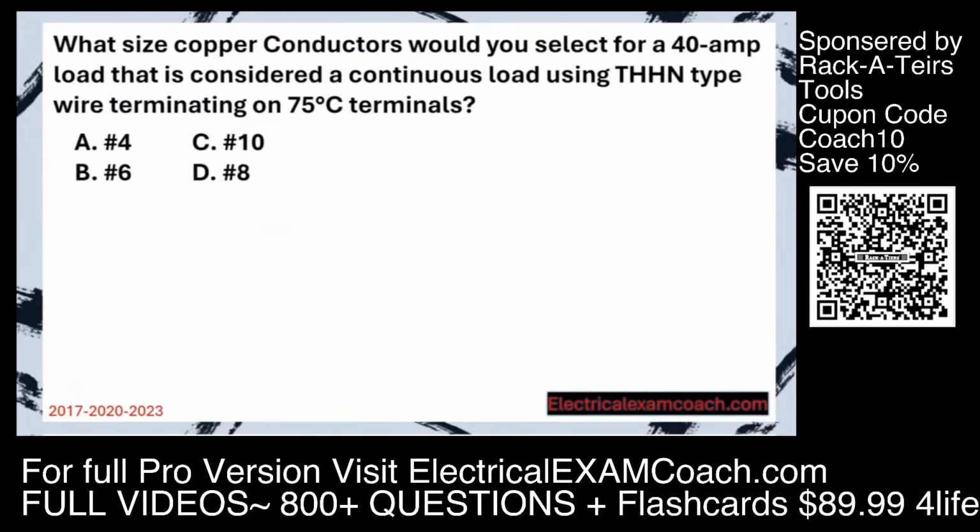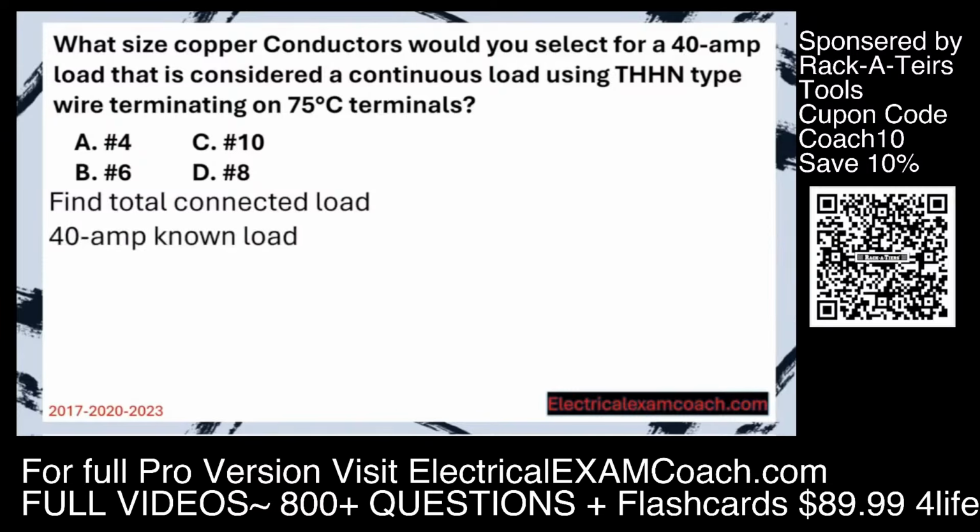What size copper conductors would you select for a 40 amp load that's considered a continuous load using THHN type wire terminating on 75° C terminals? Step 1, find the total connected load. In this case, our starting known load is 40 amps.